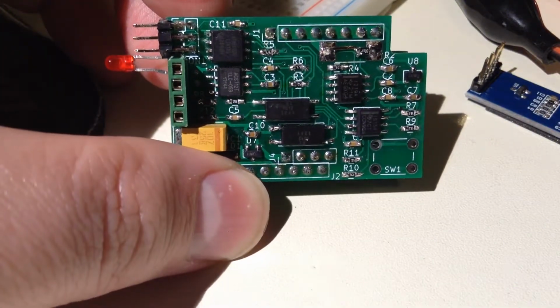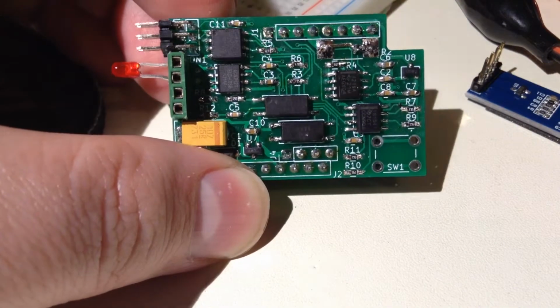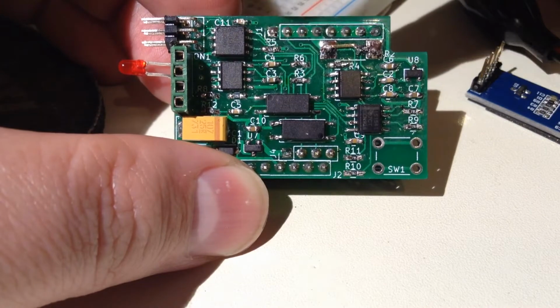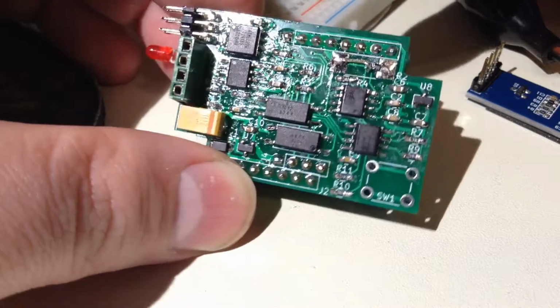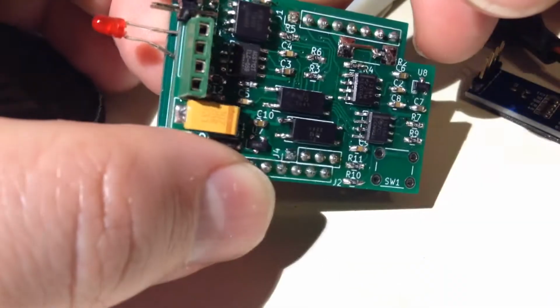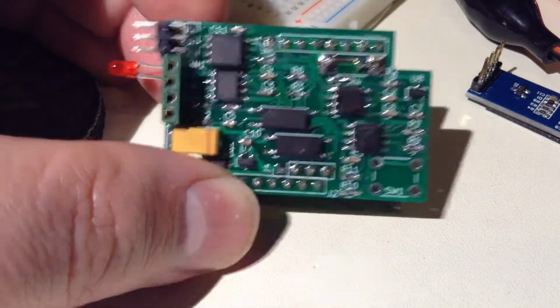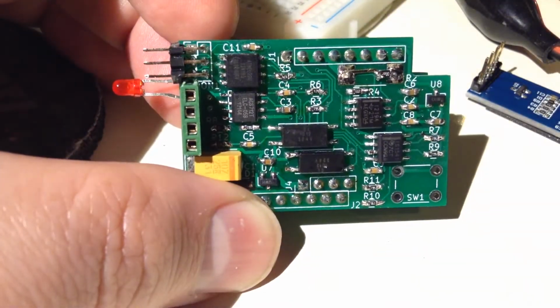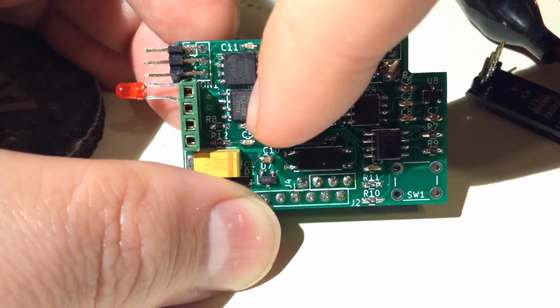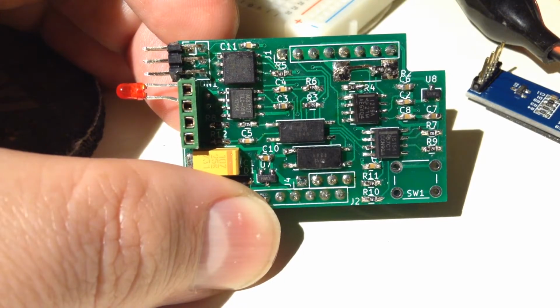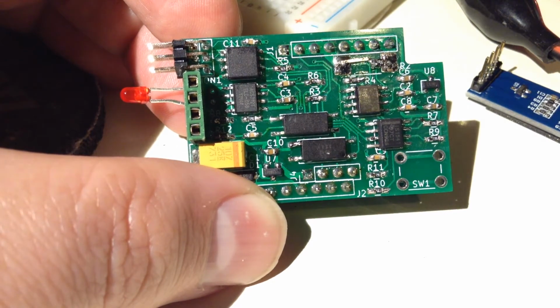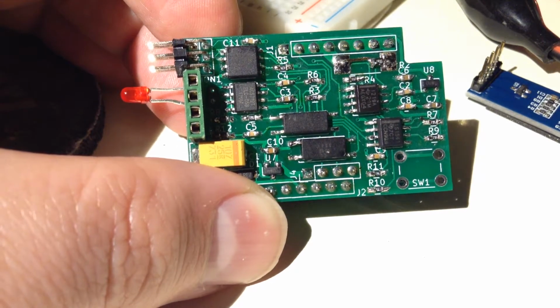So what do we have on the add-on board? We have the ATtiny, which was about 2mm too big for the footprint, so I just crushed the legs in to get it to fit. It's a long story. Then we have the ACS712, which is a Hall effect sensor, and it turns current into a voltage.